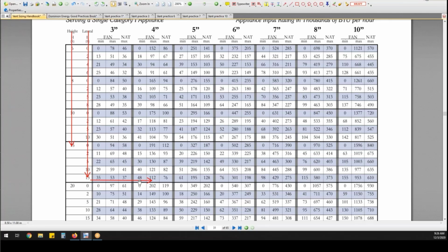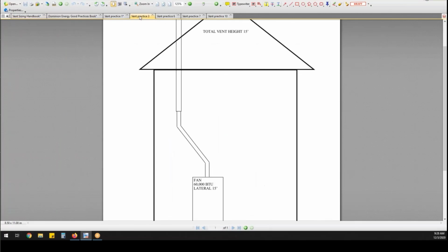The whole premise of how flues work and why we use double wall is to keep them hot. Remember on CAS testing, you always start with a cold flue. The reason for that is because cold flues have a hard time venting. You've got to keep them hot. And on fan-assisted appliances, it's critical. They give you a spread, so you've got to be between those two numbers. Because we have a fan-assisted appliance, we now have to have enough heat in there to keep it working. If we don't have enough heat energy in there, it won't work.